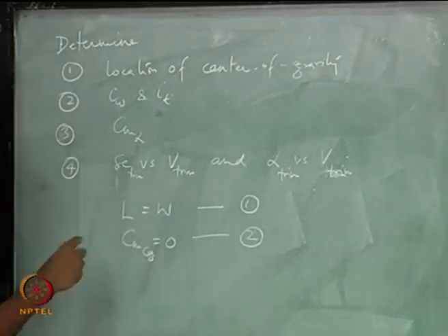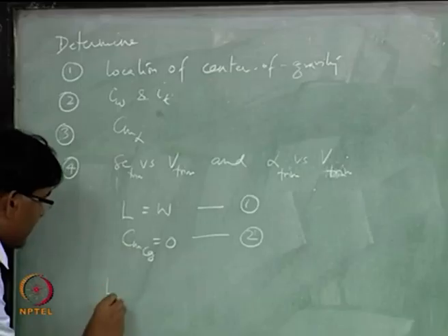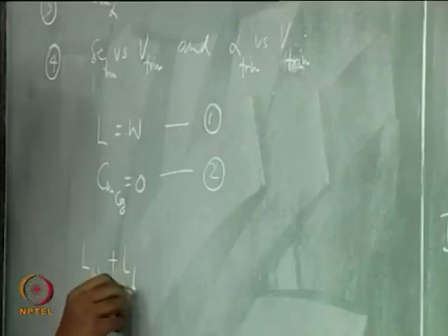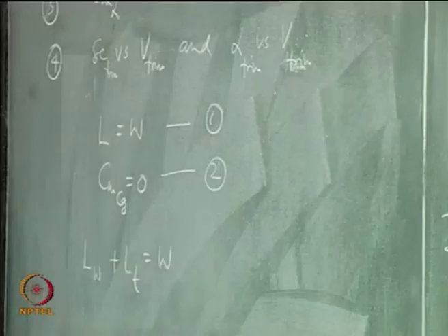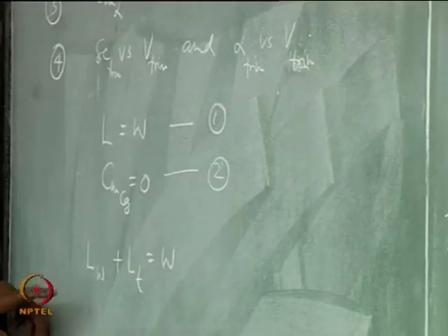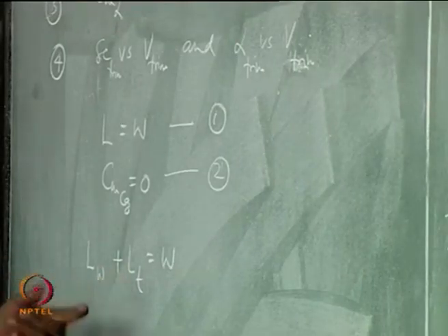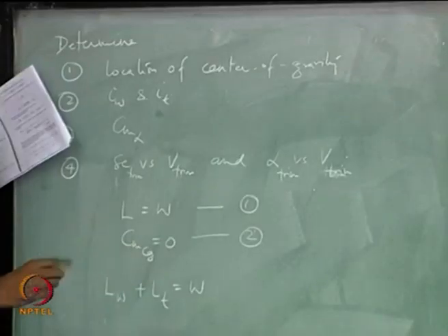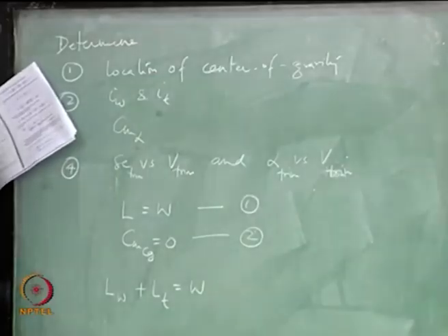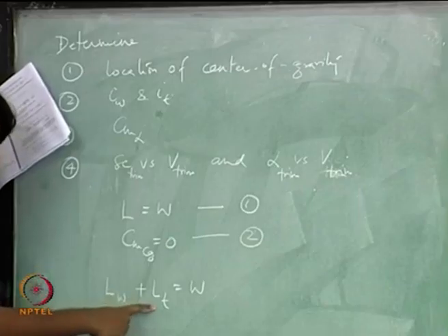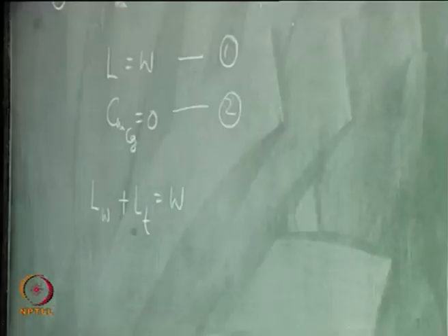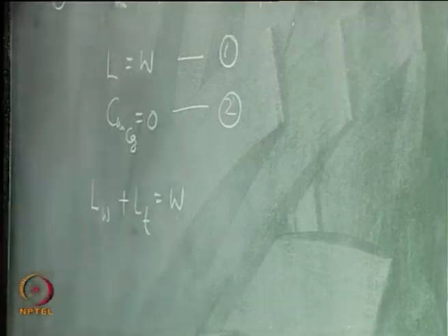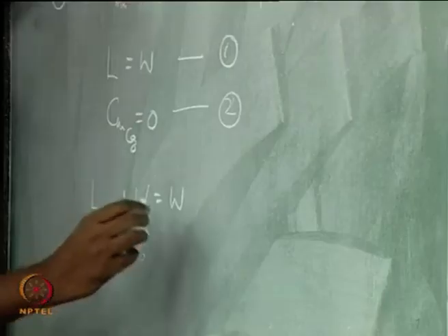What is L? L is lift at the wing, and you have to add this tail part also. But here we are saying that we are flying a condition when alpha is 0 and delta E is also 0, and the lift produced at the tail is 0. So, that is given in the problem. So, you are setting this to 0.